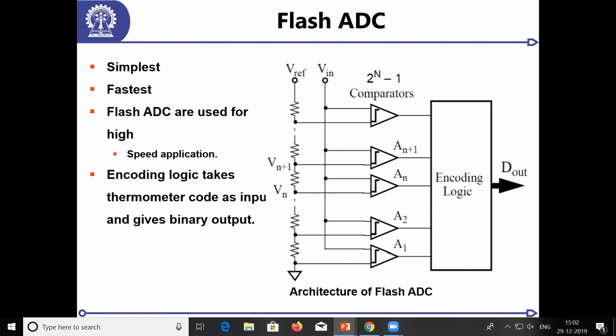That is exactly what happens when I manufacture this. I don't know what is here, but I have to figure it out. Now let us say I have this system, an R and a C. To give you a simple example, I'll put a step input here and monitor the waveform. What is the expression of the waveform if it is falling? E to the power minus t over tau. What is tau? R times C. So at any particular time, let's say t1, I will get V1 equal to e to the power minus t1 by RC.